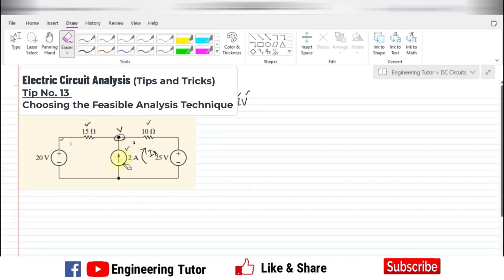Suppose we are not using the mesh current method, and we use the node voltage method instead. What is the first step? We have to identify the number of nodes. So the first node is here and the second node is here. We consider this one as our reference node, and this one as our node where we have to find the voltage. This is the only voltage which we have to find, because this one is the required voltage. So the question by using the node voltage method will be quite simple.